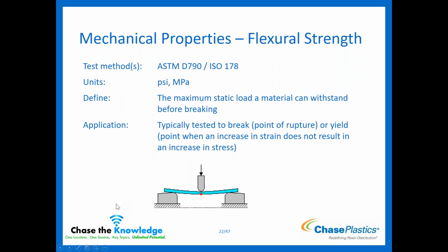So also same concept, there's also flexural strength, difference being how is it being forced? What kind of force are we putting on it? For your flexural strength, we're pushing down again in the center instead of pulling at the ends like you do for tension. And so this, same as tensile strength, it's how much force is it going to take before it's going to break.